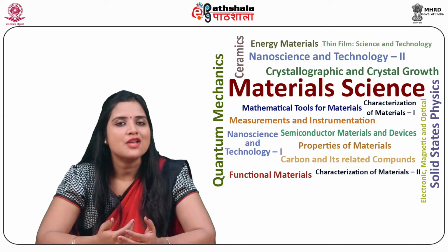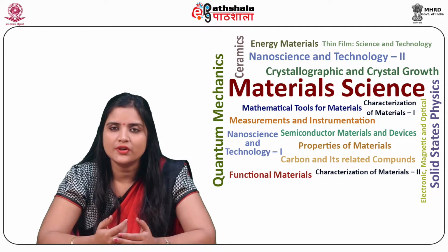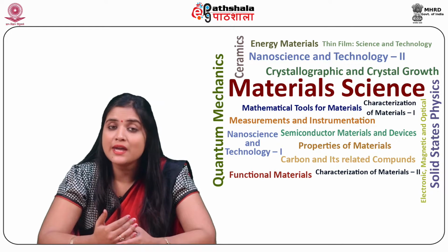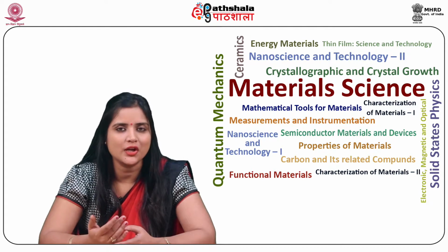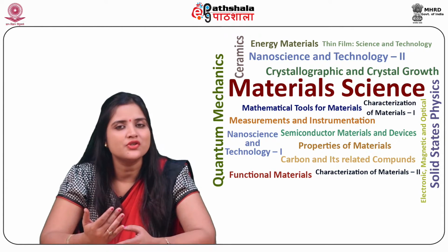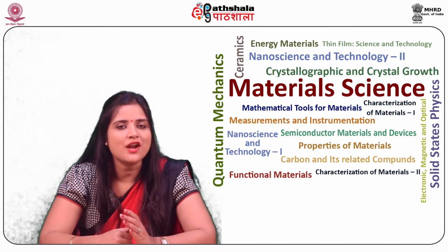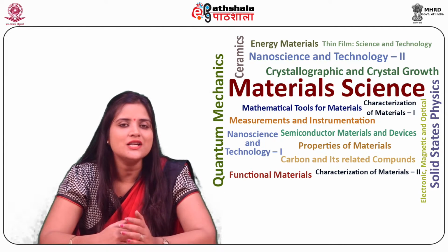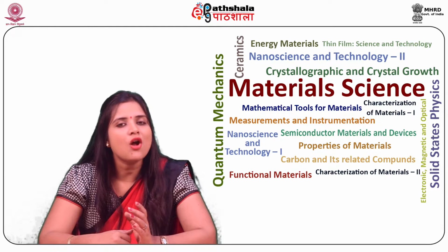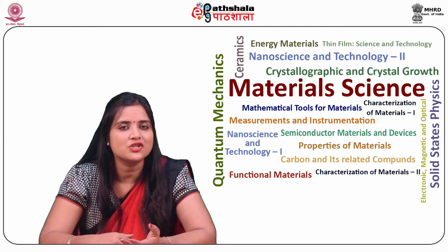An op-amp has two configurations, namely open loop and closed loop configurations. In open loop configuration, op-amp functions as a high gain amplifier in three configurations: differential amplifier, inverting amplifier, and non-inverting amplifier. In all the three open loop configurations, any differential input signal which is slightly greater than 0 drives the output into saturation because of the high voltage gain of op-amp, which is nearly infinite.